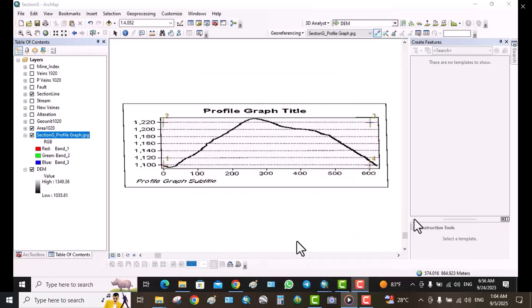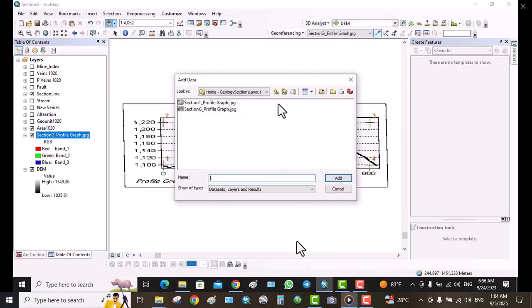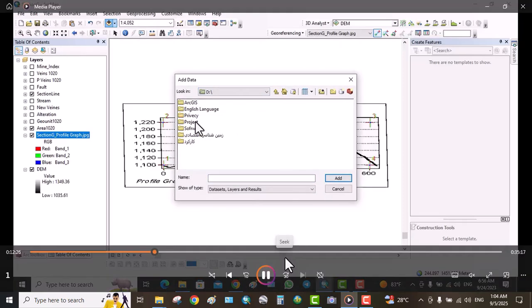In this case, you can see the profile in its place. You can also see the auxiliary points, which can be seen in green and red colors. In fact, move the point with the wrong coordinate to the corrected point. Now rectify the photo. Save the section in the corresponding folder in TIFF format.